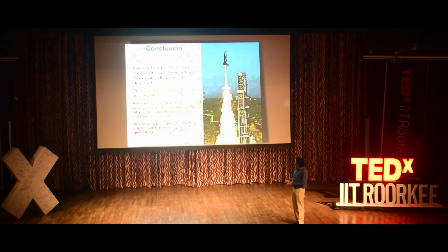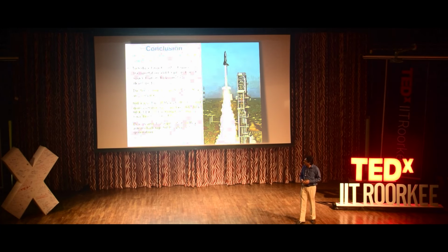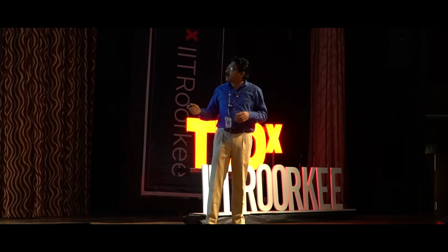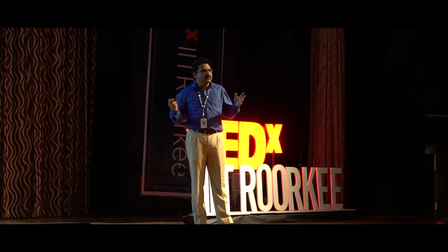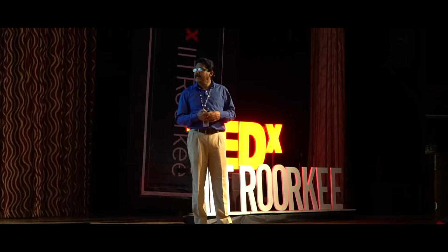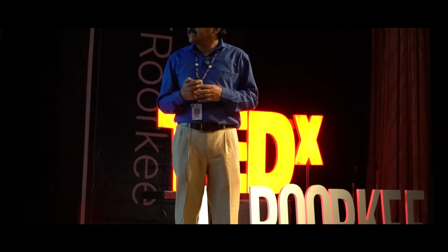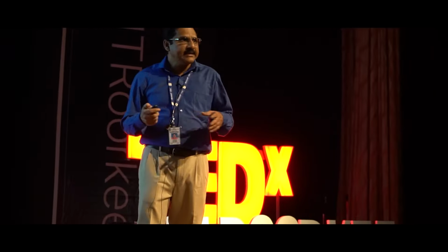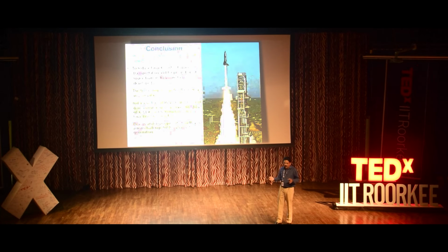So in conclusion, the present launch vehicles are expendable launch vehicles, and to reduce the cost of access to space, we should have RLVs. The technologies for an RLV are complex, and we also have our program. In 2007 we had the space capsule recovery experiment, then we had the hypersonic flight experiment in 2016, then the landing experiment and also the scramjet experiment, and these have all been successful. The design and development of an RLV is really challenging, and for the next generation there are a lot of opportunities and a lot of technologies to be demonstrated.